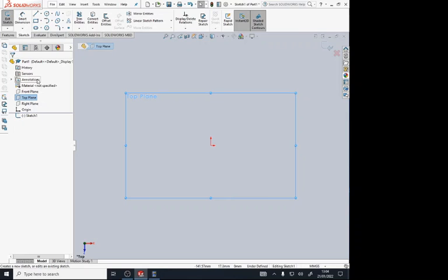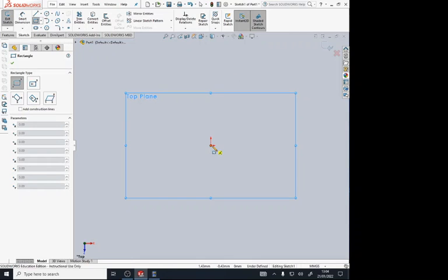So as I said to begin with, we're going to be creating a rectangular shape. If you look up here on the sketch tab, we've got these various sketching tools, and that's going to allow us to create the shape that we're looking for to build from. So I'm going to select corner rectangle, and I want to hover over this middle point here where you can see the orange dot. Whenever you work in Solidworks, we want to make sure, if we can, that that's the point at which you start drawing from on any plane.